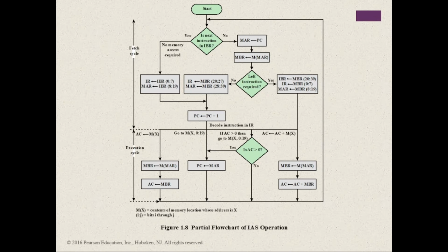Why the indirection? These operations are controlled by electronic circuitry and result in the use of data paths. To simplify the electronics, there is only one register that is used to specify the address in memory for a read or write, and only one register used for the source or destination. Once the opcode is in the IR, the execute cycle is performed.